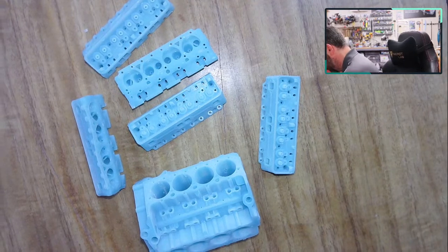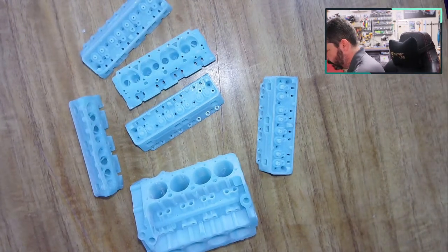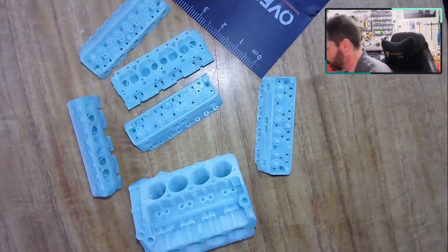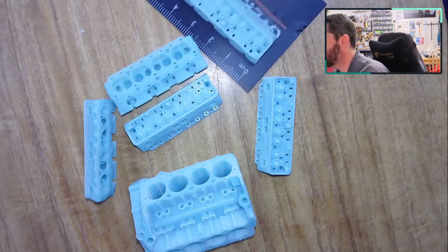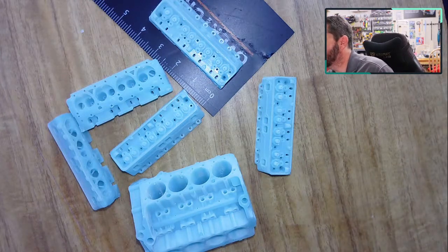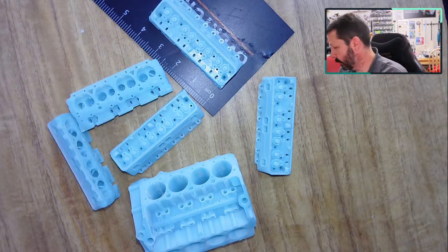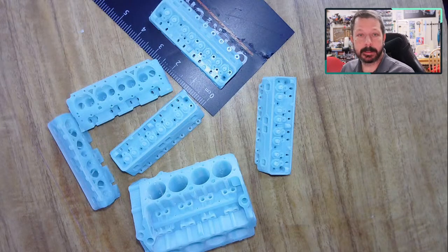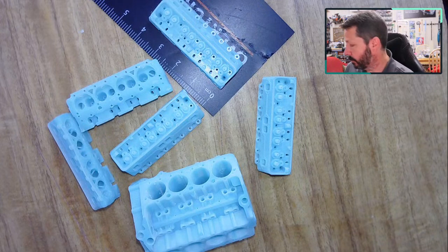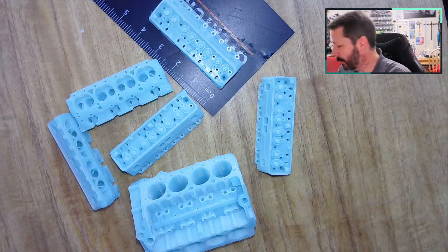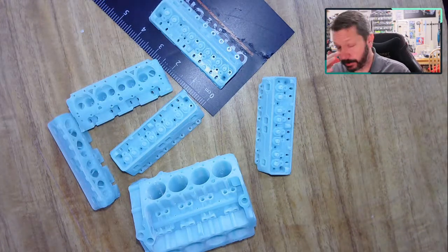Here's some centimeters, so you can get an idea of the size of these things. The whole thing is 40 millimeters long. So some of those details are sub-millimeter level details. And again, even that resin printer can go much smaller on the layer thickness. It is limited on the pixel size. It is a 4K screen that's, what did we say, 8 or 9 inches wide, 7 or 8 inches wide, I don't remember now. But there are higher resolution screens out there.